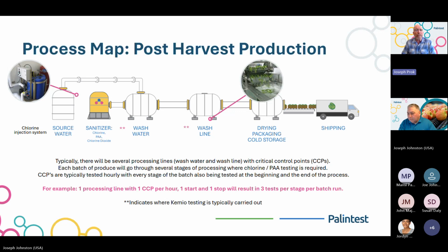So on this line, you'll see on this drawing, you've got two asterisks here, one in front of the wash water, as well as in front of that rinse line, or maybe even post rinse. And these are representative of a critical control point as a part of a hazard plan to be able to monitor and manage every single critical control point within the process.